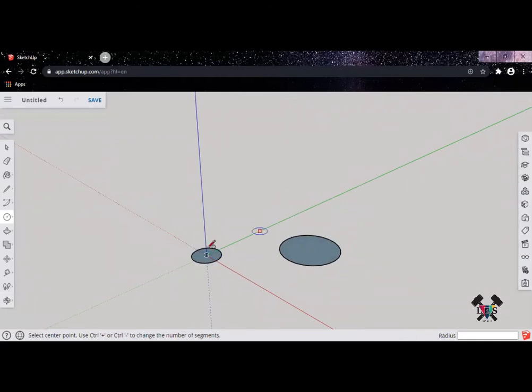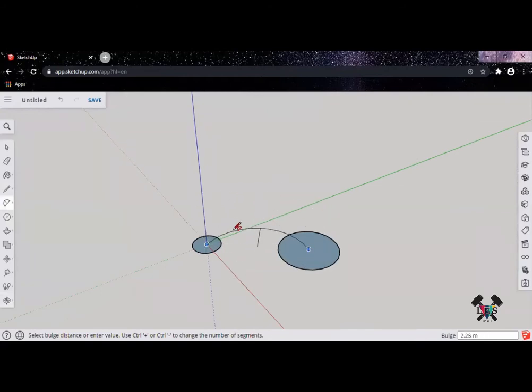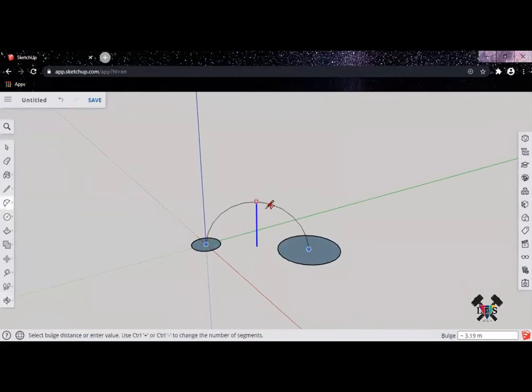One thing I could do is make two circles like that, and then press A on the keyboard to create an arc length. Another way is over here on the left again; everything's here. You can click this, or this, all arc lengths are just different ways of doing it. Press A, click the center, and then you click on the center and see these lines when you're making them. Sometimes you don't know which axis they're going on, so I'm just going to press up for this example.